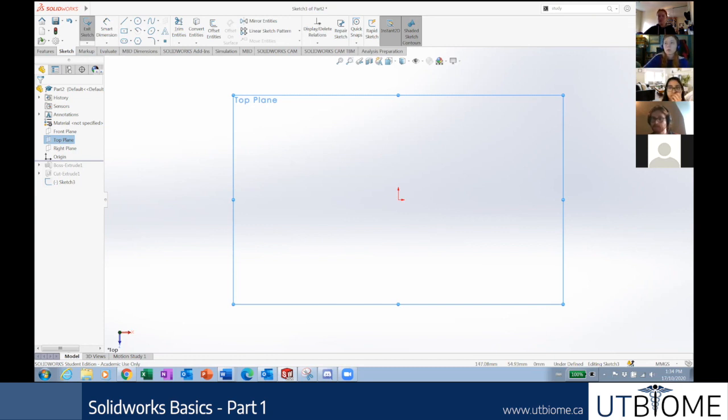What these are is this red X means you're discarding your sketch, whereas this blue arrow saves it. Discard sketch just means whatever you just did is complete garbage. You never want to see it again. But if you want to save it and exit out, and I'll show you some reasons why you'd want to do that, then you press the blue arrow. So red means whatever you just created needs to be dead. Blue just means you're going back. It's totally cool.